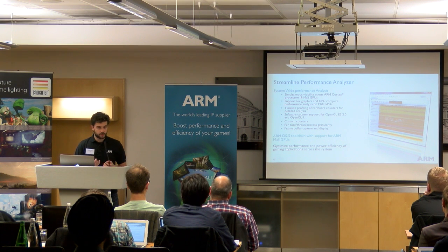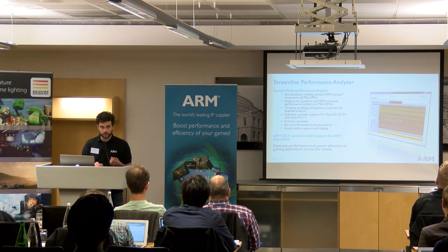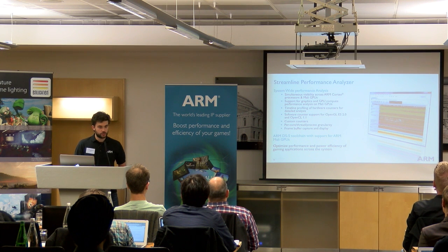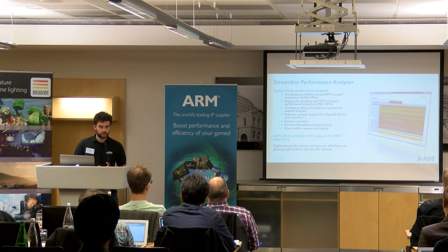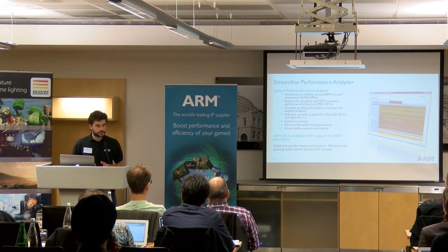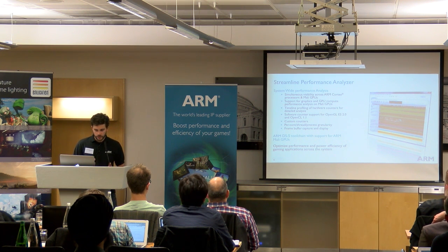Then we also have support for the Mali GPUs, again, hardware counters coming from the hardware. So when the GPU is running, it's collecting data like how many load and store instructions it's running, how many stalls, how many texture fetches have been decompressed, and so on. There are more than 300 Mali GPU counters that you can choose from. We also have software counters, which is what we call events that come from the driver stack, and even the kernel stack.